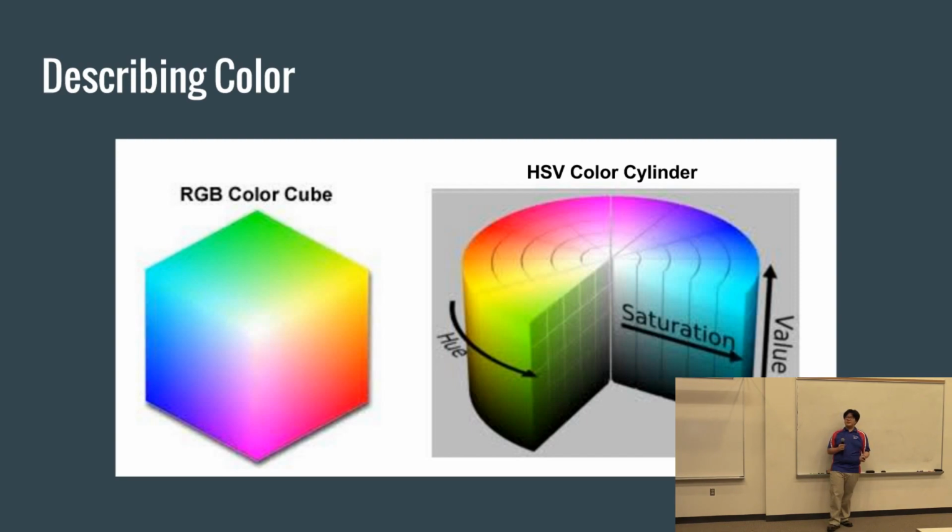The reason I make that difference is that in order to actually find that target in our image, we use something called HSV thresholding. Basically, you take an image. Images are just made up of a huge array of pixels, right? Every pixel is a certain color. And we say, filter out all the pixels except pixels of this certain color. If you have a camera pointing at the target, remember the target is surrounded by something called retroreflective tape.